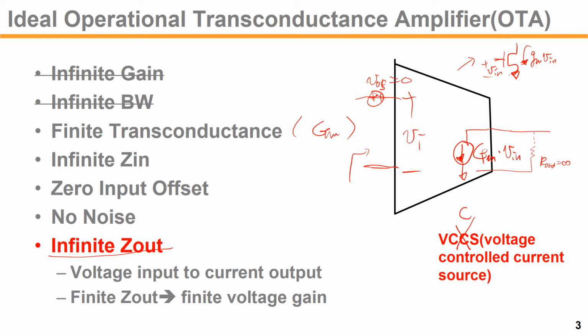So for our ideal current source, we want to have output impedance infinite, so that the current output is only delivered to the output load condition at the load. So this R out should be modeled inside this model. So R out is modeled equal to infinite in this case, for an ideal case.